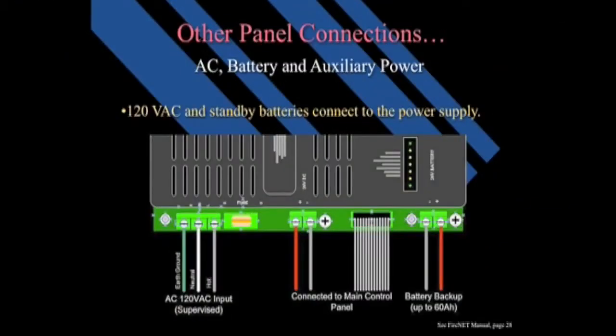The 120 AC and standby batteries connect to the power supply. Inside the power supply is a jumper that can be removed to set the power supply for 220 volt operation as well.